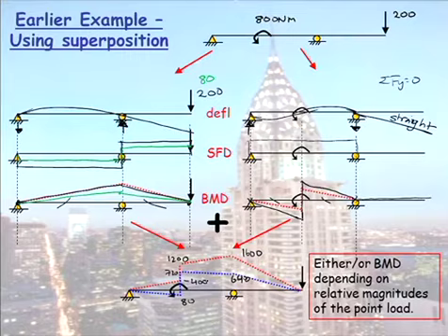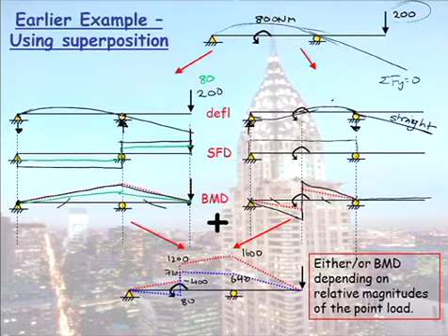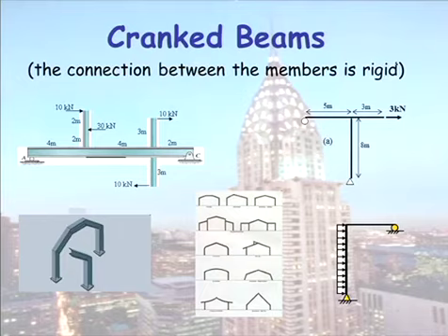So I just want you to realise that those two previous problems I gave you, in effect, had the same basic breakdown, the same bending moment diagrams to superimpose, but because their values were different, they came out looking differently. And as such, when you look at these combined deflected shapes here, when you had the 200 load applied, it was simply popping up because the 200 was so big. But when that became 80, then the effect of the moment was enough to actually bring it down. Yep, good.